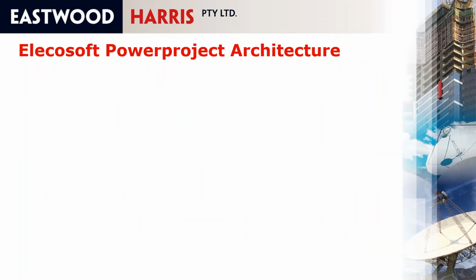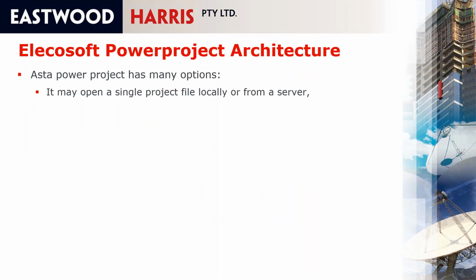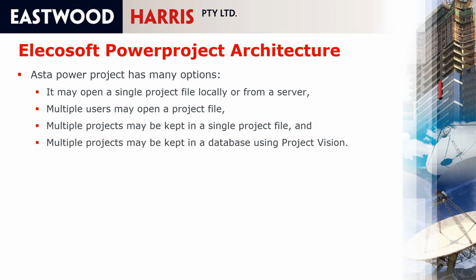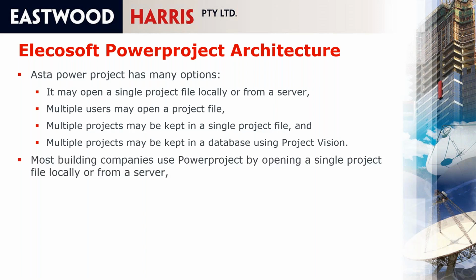If we have a look at Elecosoft Powerproject, Powerproject has many options. You can open up a single file locally or from a server. Multiple users may open up a project file, and also multiple projects may be kept in a single file. And finally, if you want to run it in a similar way to Oracle Primavera P6, you can use Project Vision and have all your projects in a database, and then you can open them from the database. So it's got a lot more flexibility. Most building companies that I know of use Powerproject by opening up a single project, usually from a file server.